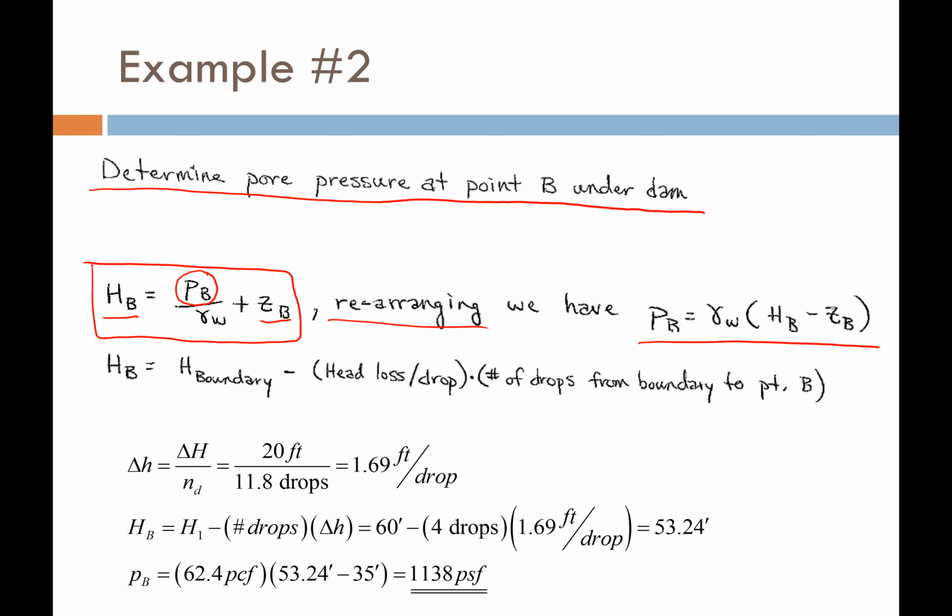Well, where in the world do we get total head? Well, we get those from the equipotential lines. Think of the equipotential lines as energy contour lines. And if we have labels on our energy contour lines, then all we need to do is interpolate where our point is relative to the closest equipotential lines, just like you're reading a contour map, like an elevation contour map.